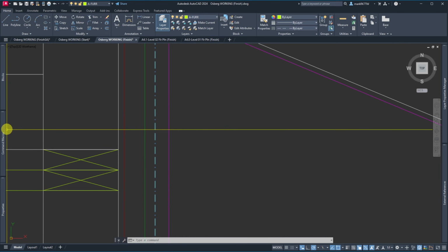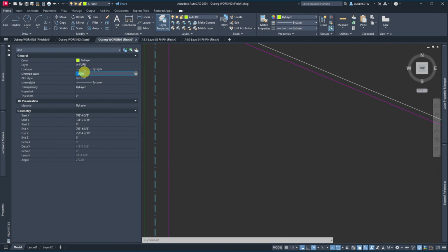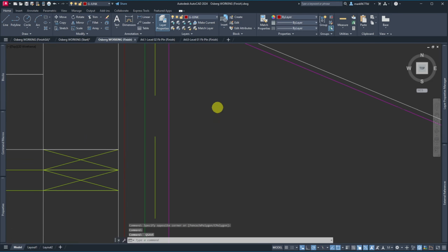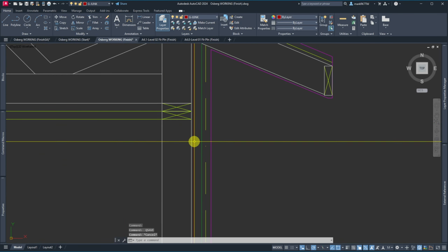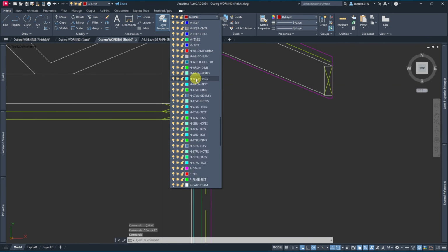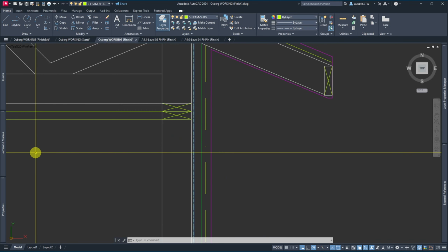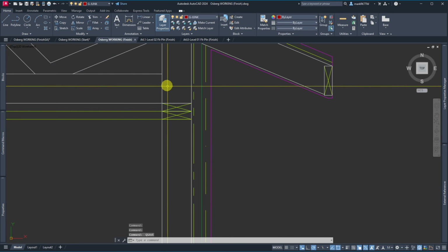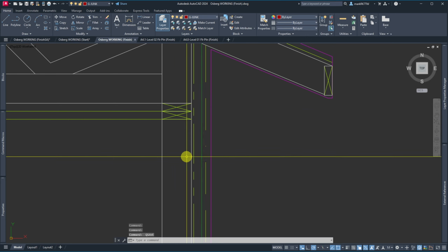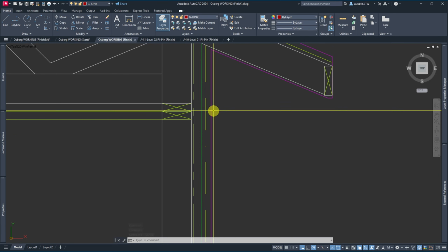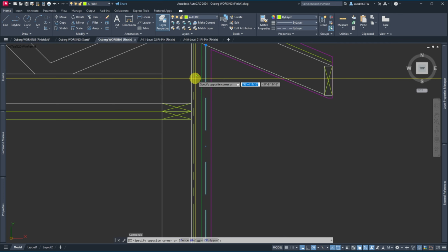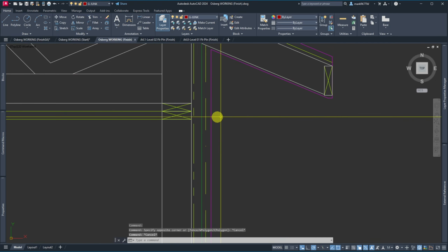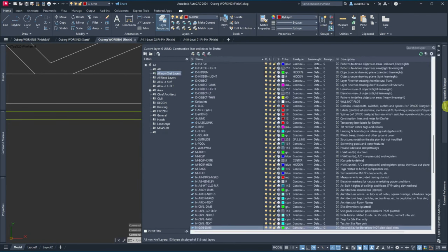And while it's still selected, I want to come down here, change this to 12 to make just the line type scale show up better. Here is going to be in my S layers because it's a structural layer for sheeting. And again, just change that LTS to, and you can see there are different looks. And hopefully they are, yeah, they're color 60. That got me in trouble a little while. I had to go do a whole bunch of changing on stuff. So